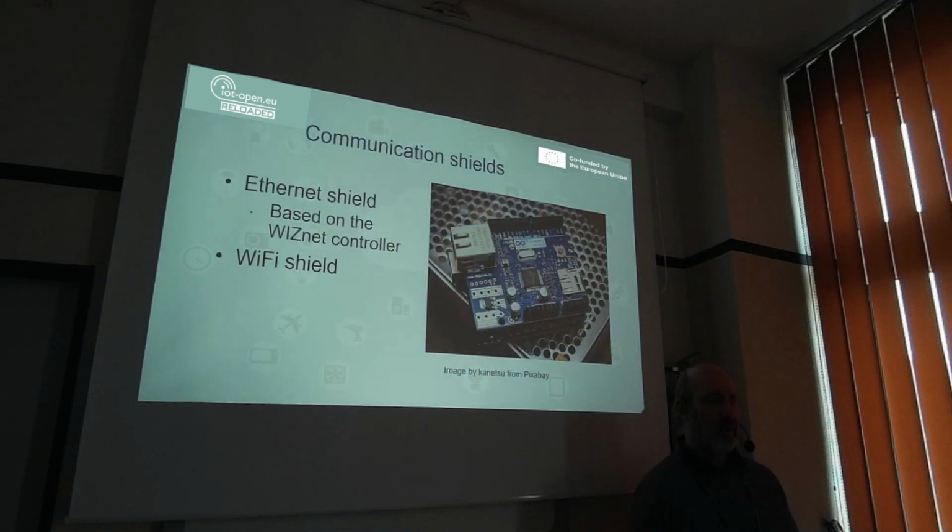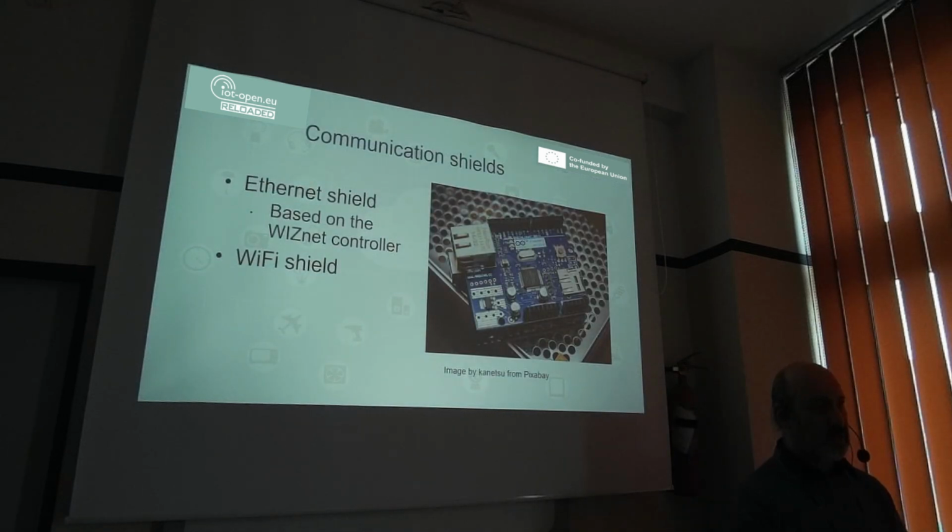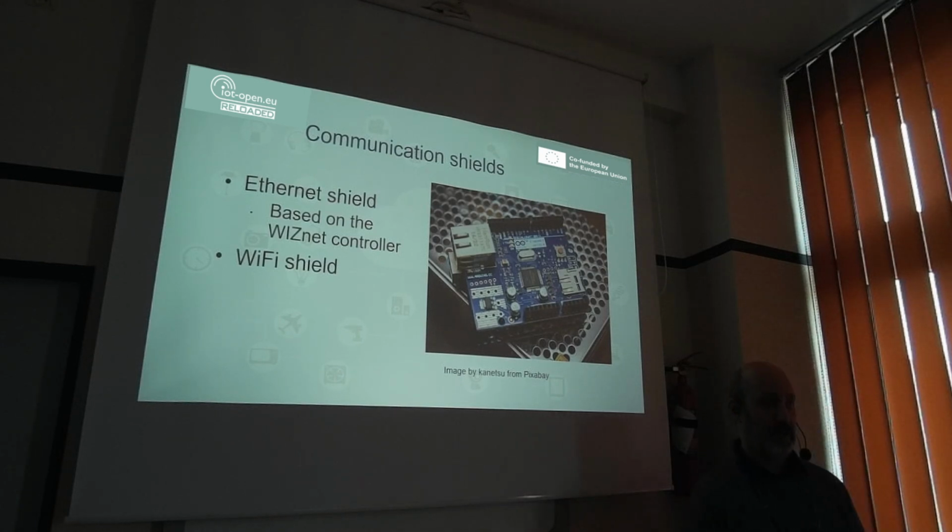As we said, Arduino itself cannot be an IoT device because of lack of communication, wireless communication or wired communication in the network. So there are shields that extend the possibilities of Arduino boards, like for example a communication shield based on WizNet controller.